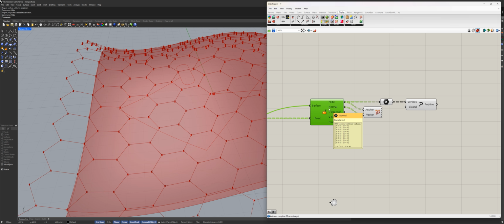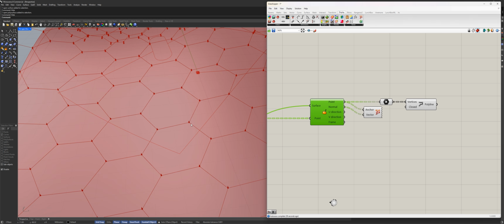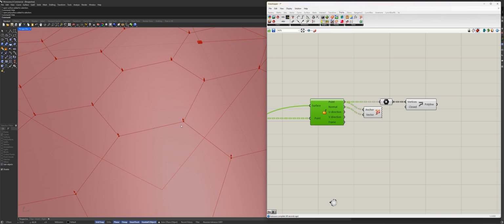It does a lot of calculations. And more importantly, it calculates not the normal vector, it calculates a curvature vector. Basically, it calculates our formula, which I explained in the previous lesson, to the second derivative and finds a curvature vector. Now, the curvature vectors are not unitized. They are different in length. Some of them are longer, some of them are shorter.